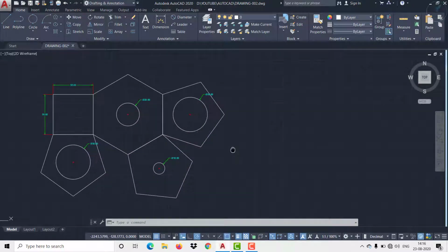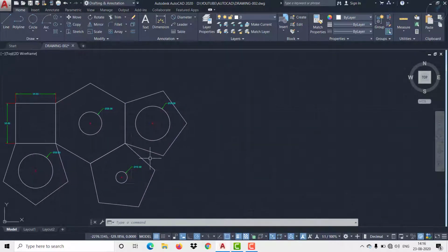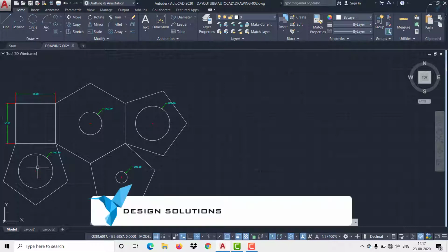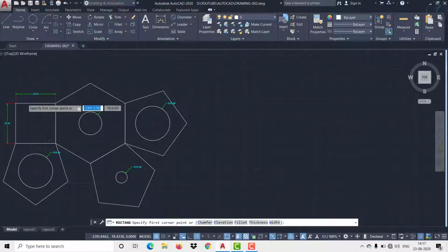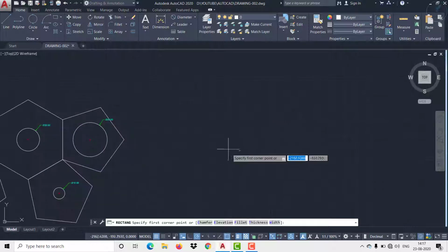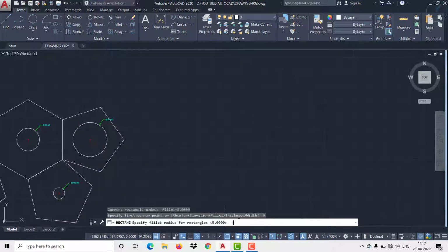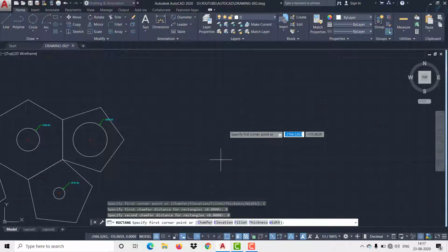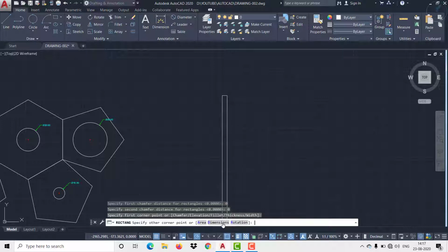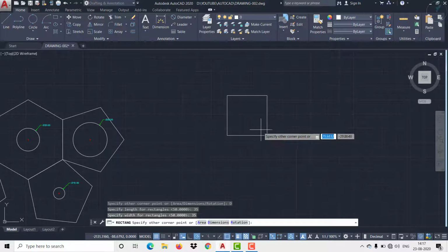So this one we can create with one rectangle, or as it is a square, we can use the rectangle option to create that square. Then we have to create this polygon over here, but we have to use the edge method, not the center method. So first I'm going to rectangle. If you see 35, 35, if you have fillet, make sure it is 0, and if you have chamfer, make sure that also is 0. So now click, already we know the dimension, that is 35 cross 35, enter. So click over here, create it.